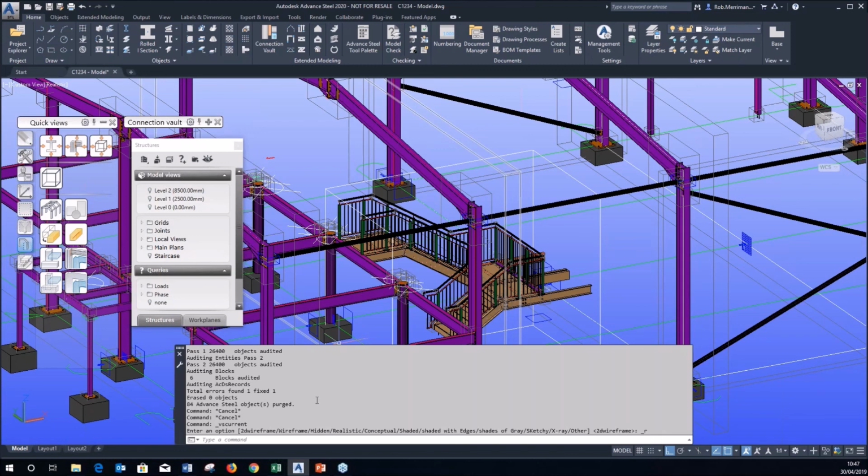But in the background, it's still referencing each of those 90%. Sometimes we've had audits that have cleared out like 80,000 Advanced Steel elements. It's a bit like the AutoCAD purge tool. When you delete things, they are not completely gone. There are still references in the background, so the audit goes through those references and clears out that kind of information.